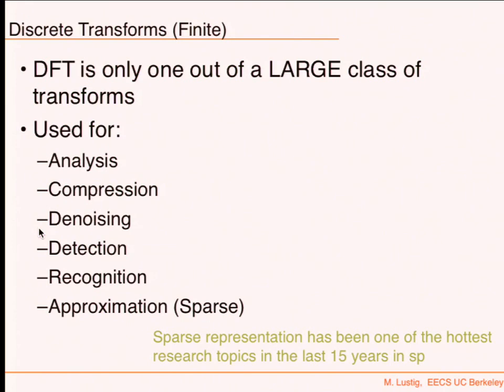That's because it's sparse. There's only one component there. If it wasn't sparse, if it was a whole spectrum, it would be hard to say, since it would be buried here and buried here. But if it was just a few coefficients, that would be easy to separate. Then you can think about how to denoise: you grab it by the neck, clean the rest of the stuff, put it back, do an inverse Fourier transform, and you've got yourself a denoised signal. Okay? So here's an example.